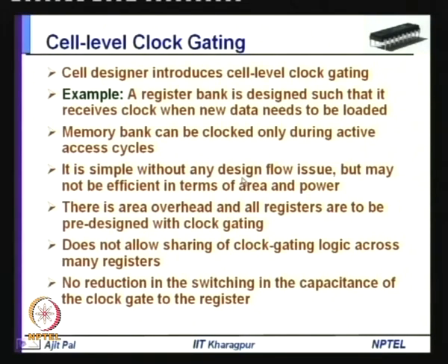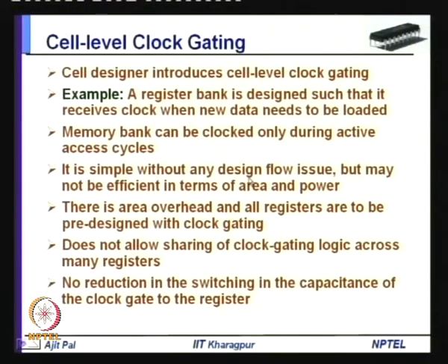So, it is simple without any design flow issue. As I have already told, it has no impact on the design flow, neither the designer has to bother about it, nor an automatic tool needs to introduce clock gating hardware, because it is already built in as part of the hardware, but may not be efficient in terms of area and power. For example, whenever you are doing it at register level, each register has to be designed with built in clock gating hardware. So, there is no question of sharing a single clock gating hardware for a large number of registers.